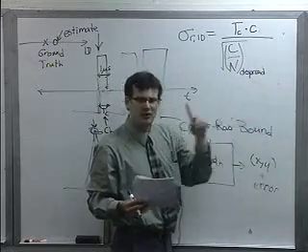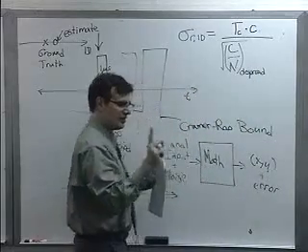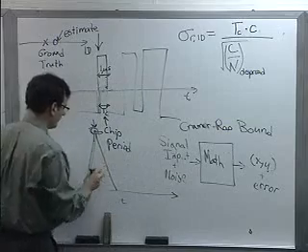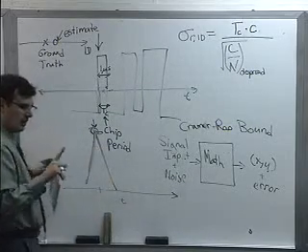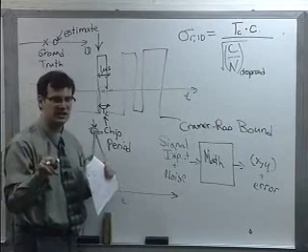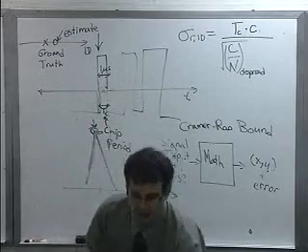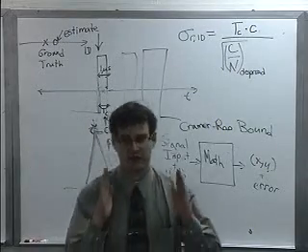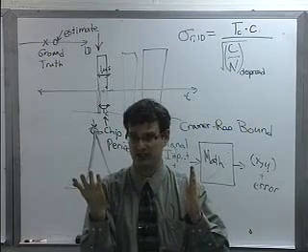And that's good, but we know that our GPS receiver is a little bit better than that. One of the things you can do to improve your signal to noise ratio is that you don't have to do just one bit. The processing gain for one bit is about 40 dB, because it's got a 30 dB processing gain for a single code, 1,000 chips in the code before it repeats itself.